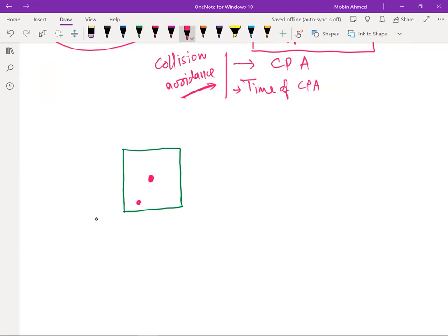Now when it comes to this point, there is going to be a plus or minus error because it is not at the center of this window. Due to that error, the system will come to know, and this window will also shift along with the target, because it knows how much and which side the target has moved. The window is always going to keep the target at the center.